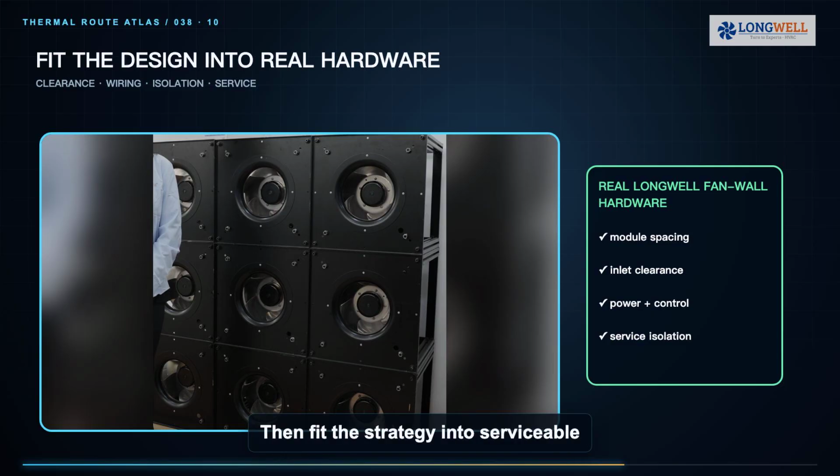Then fit the strategy into serviceable hardware. The moving Longwell fan wall footage shows a real modular arrangement, but it does not prove this example's airflow or pressure. Use it to inspect module spacing, inlet clearance, frame stiffness, power and control routing, safe isolation, lifting access and replacement direction. Confirm that a module can be removed without exposing personnel or allowing uncontrolled reverse flow, and that the selected fan curve covers every scheduled state.